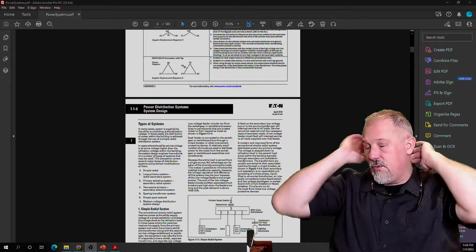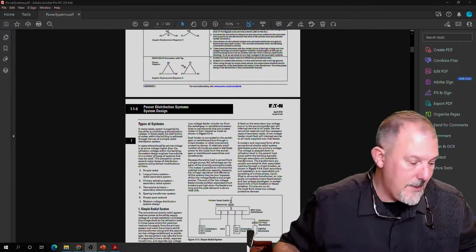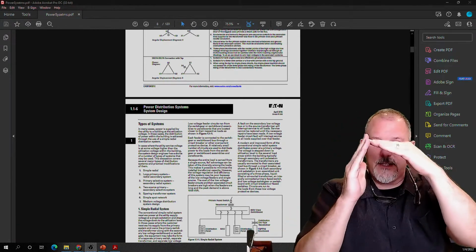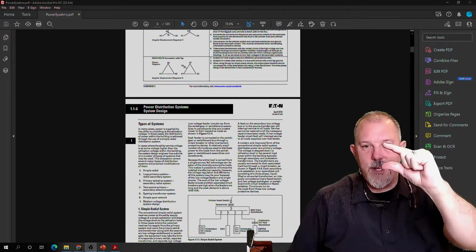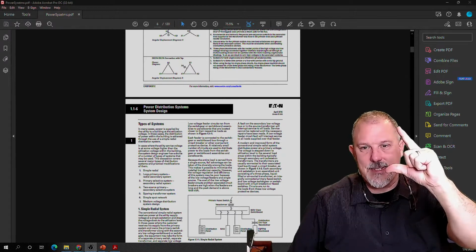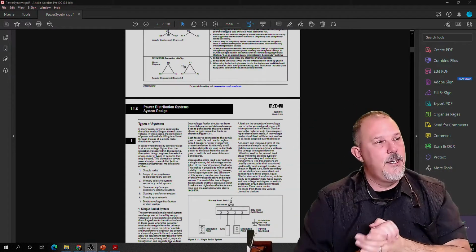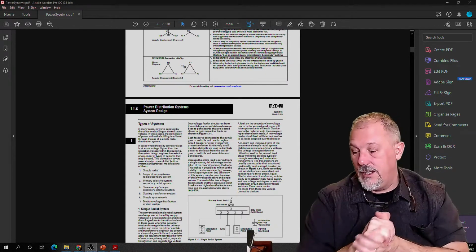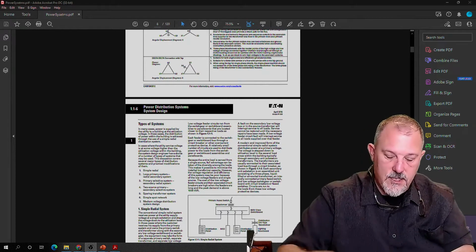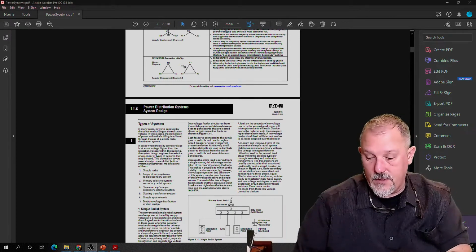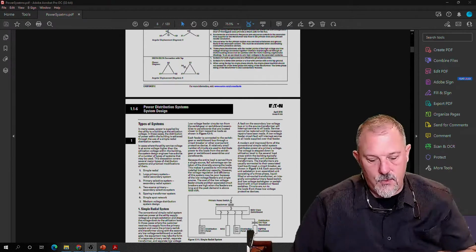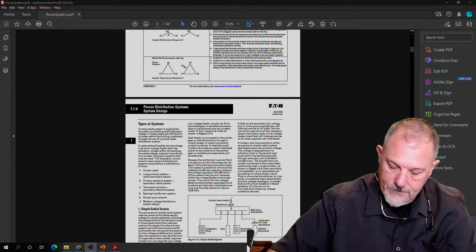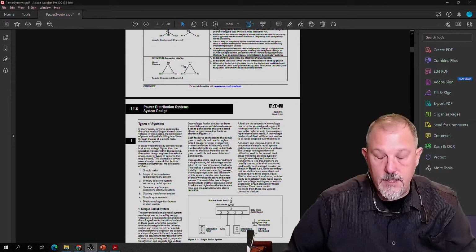really be careful and do a voltage analysis when you are applying inductors, because remember, you're taking a triangle. Your power factor is going to go like this, and your hypotenuse gets more. So you're adding more impedance to the system, and that will impact voltage. And you may address the fluctuation issue, but you may now have a different issue. So it's a balance. I don't believe there's any silver bullet for any of these things. When it comes to a system, you have to really do an overview.